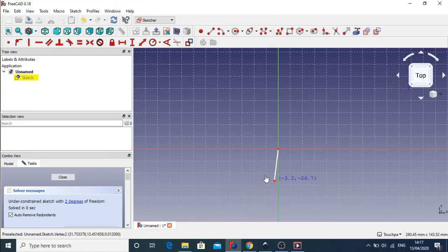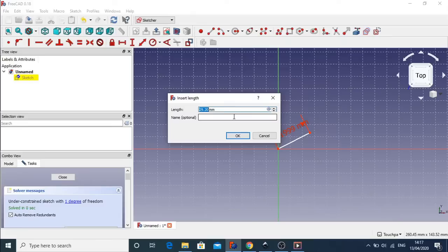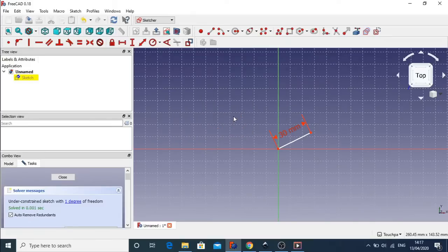So rotation around here, and so I want to constrain the length of this, and I'm going to go to 30. Now it's got 1 degree. That's it. Now it's got 1 degree of freedom, because if we constrain the length, we can't actually stretch this in and out here. So this is what we want: 1 degree of motion. I was right the first time.